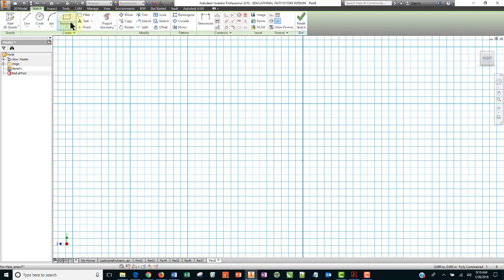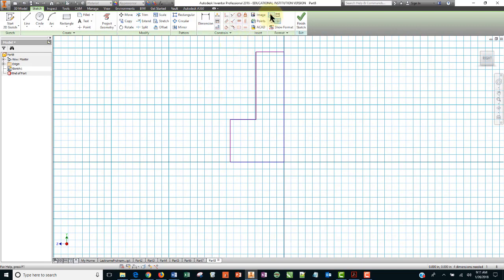So I'm gonna just start drawing that L-shaped thing. Even though I know the dimensions, I'm going to just let the geometric constraints that are created as I sketch keep my figure shaped correctly and then now dimension it. So let me go and create an axis of rotation for our revolve, and now dimension from here to here is 0.375, and from here to here is 1.